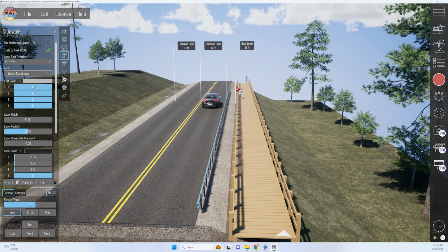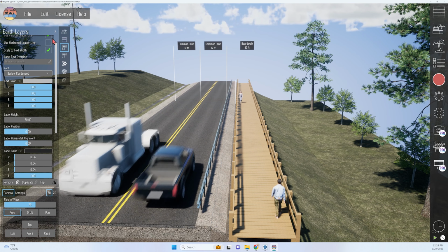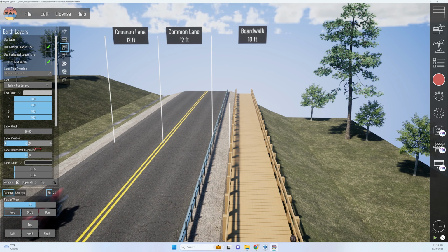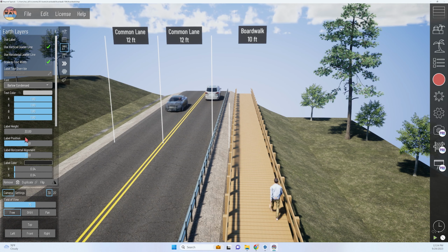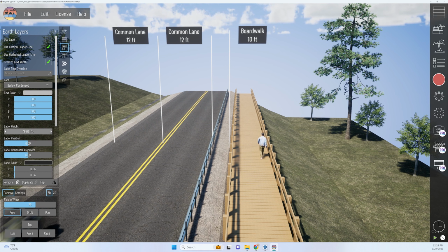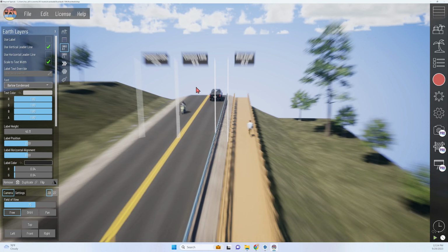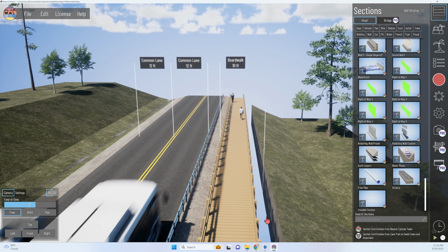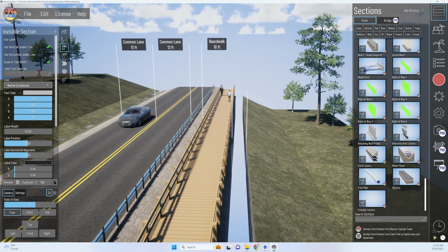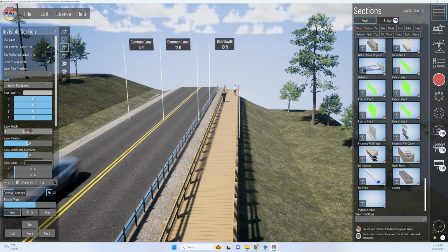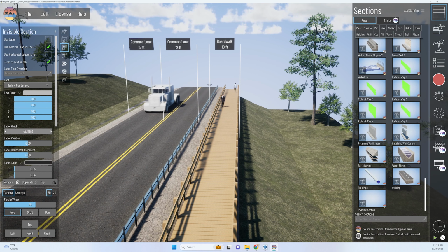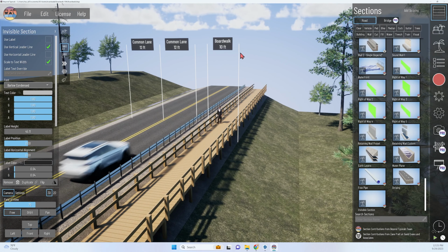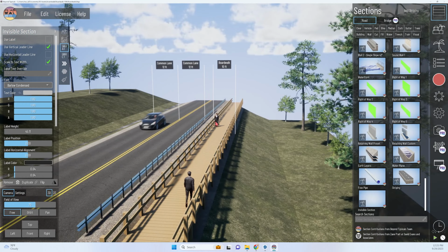If you wanted to see those vertical leaders, I've mentioned this in a video as well. We've got this earth layer section here. It's got a vertical leader line. We can just use that similar to our invisible sections, where I move that label height up just to match the other vertical leader stems. And I can also put an invisible section here on the right side of this and make that 0 feet wide and move the label height of that 0 foot wide invisible section so that its vertical leader also extends upwards to match the other labels in the section.